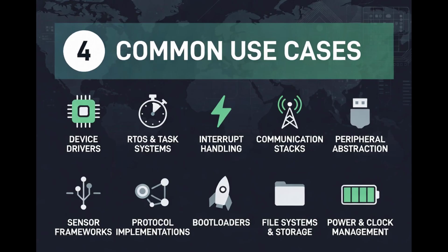In real-time OS and task systems, patterns enable event-driven scheduling, synchronization, message queues, and task coordination. As for interrupt handling, callbacks and deferred processing patterns reduce ISR latency. Heavy work moves out of interrupts into worker tasks.